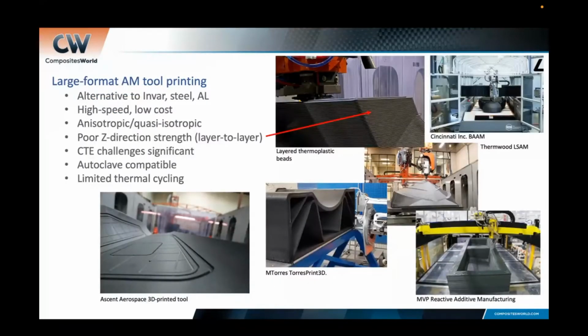When you're making molds using additive manufacturing, we're talking about layering a thermoplastic material, usually through an extrusion head, onto a printable surface. It's typically built horizontally, but as you can see with that mTORUS system, you can also print vertically. The advantages of this system are pretty significant.